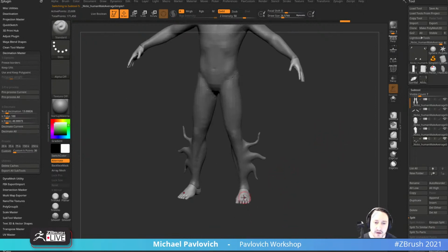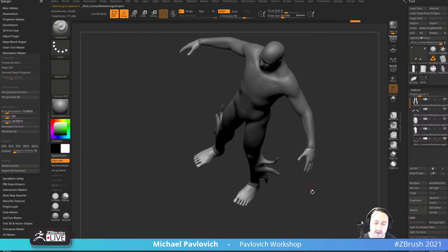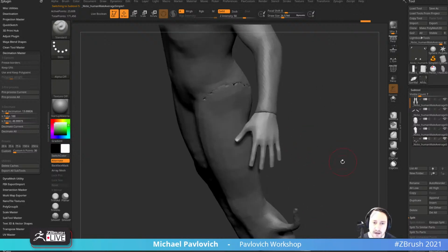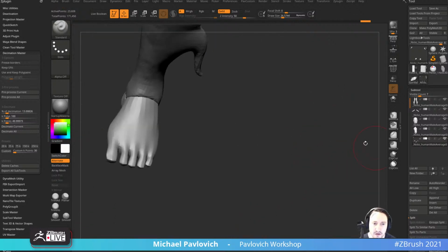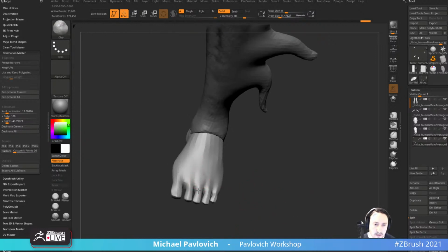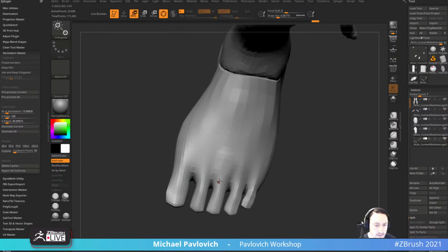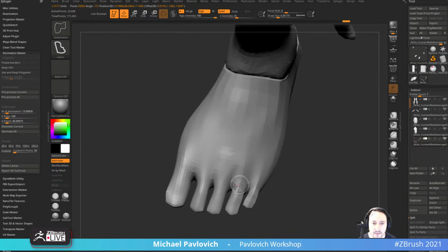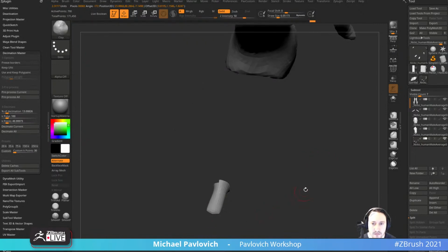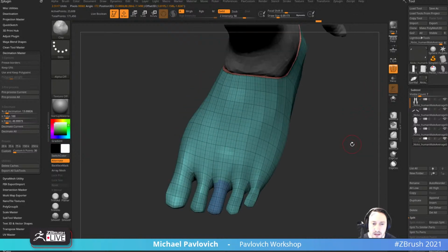And that way I don't have to worry about the toes closing up on me because it's just geometry. And in fact, I can go through here. If I want to sculpt on one toe, I can maybe even turn on some auto masking. And if you saved your polygroups, which I didn't, I made it all one polygroup, but you can get them back and just hit W and Control drag out and then invert that, hit Control W. So now this will be its own polygroup here.